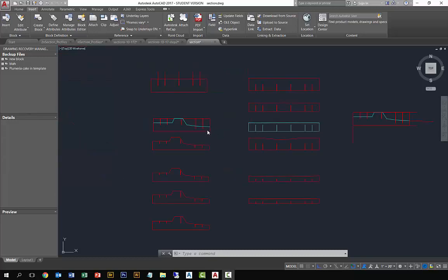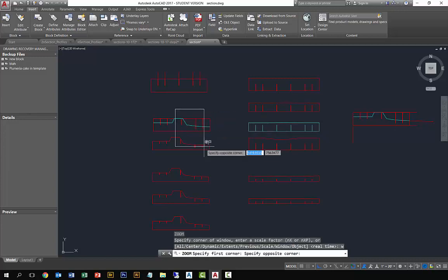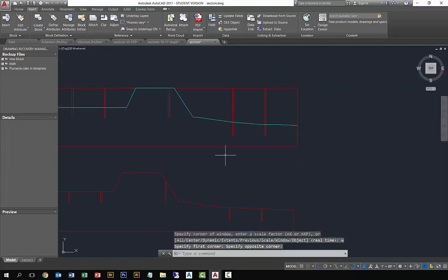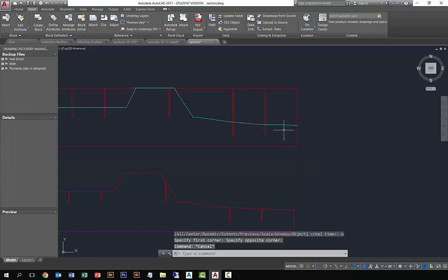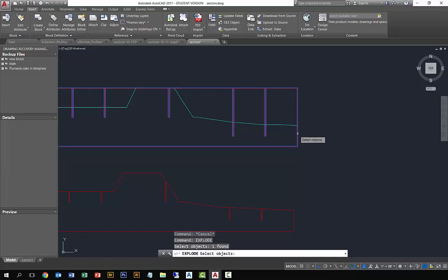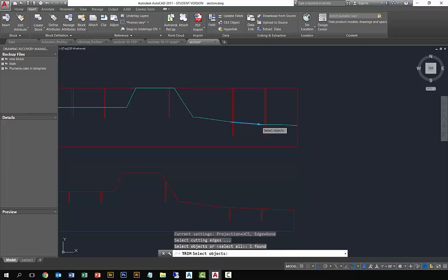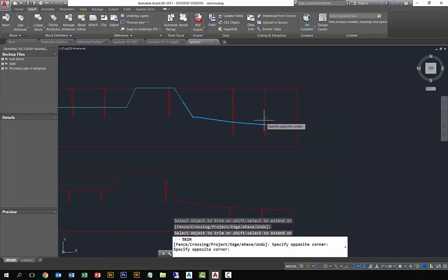All right, so now you can see where I'm headed. This is where you're going to want to end up, which is to line up your jig with your section and then begin to edit. So the red jig is a polyline, so you're going to explode it. Hit enter, and now you're just going to go through an exhaustive number of trim and edit commands so that you can actually get a shape that the knife cutter will be able to cut out from the chipboard material.